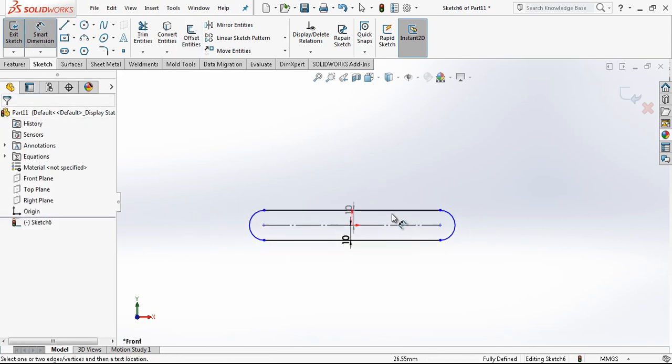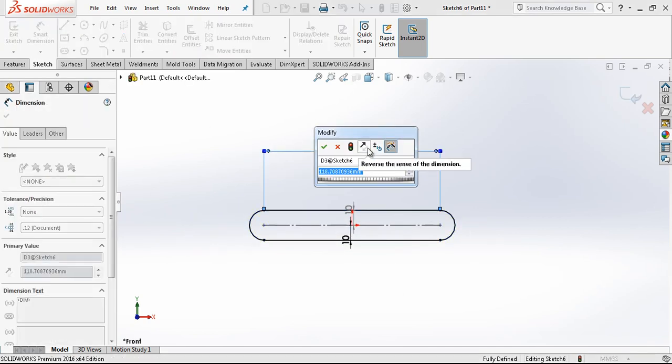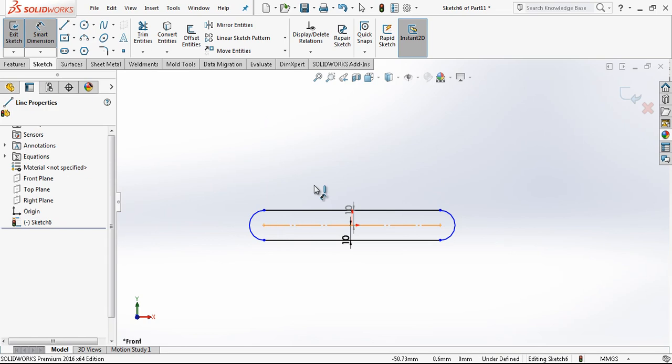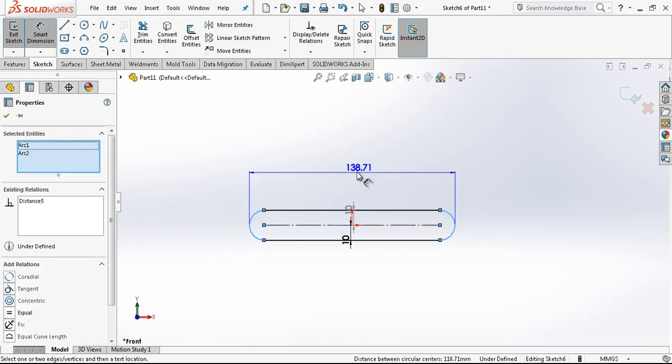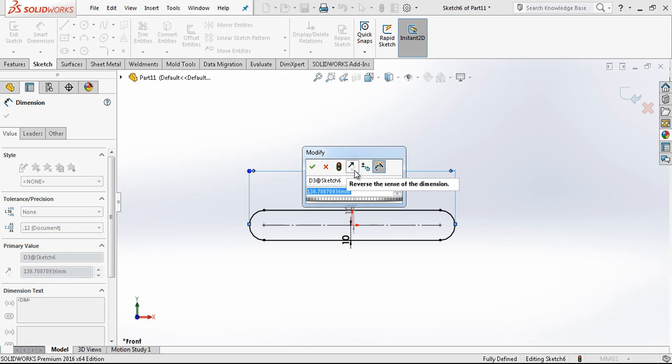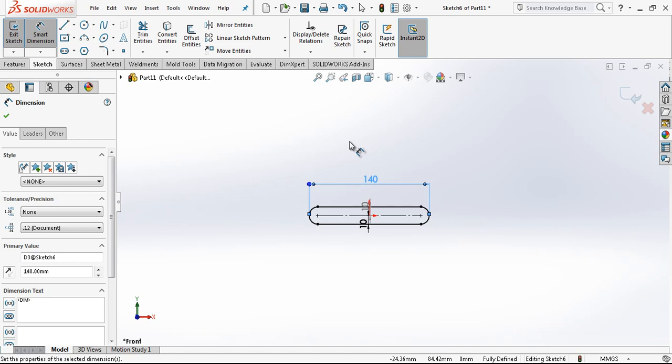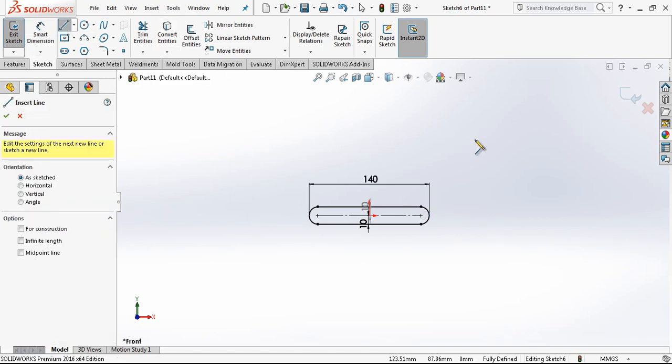As you see, with one line you have so much. If you don't want to give the center dimensions, with shift, if you choose two objects, especially circles or semicircles, you are also allowed to give the outer dimension. I also want you to know that there was one other option there.